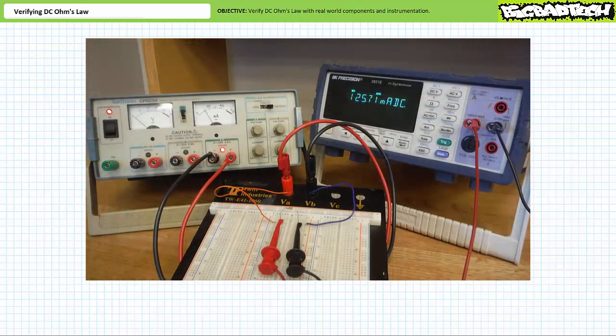Here the DC power supply is current limited to a maximum of 125 milliamperes. When we turn on the power supply, an ammeter incorrectly configured in this fashion demonstrates roughly 125 milliamperes, our permitted maximum, flows through the ammeter. The source indicates it's in an overload condition by illuminating the overload LED. Again, we've current limited this source to 125 milliamperes.